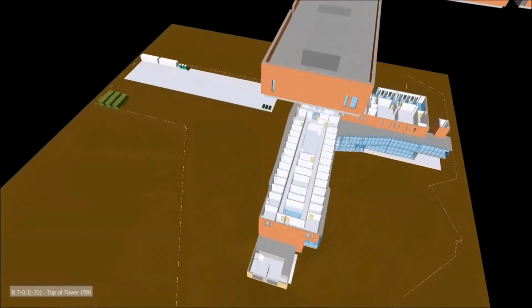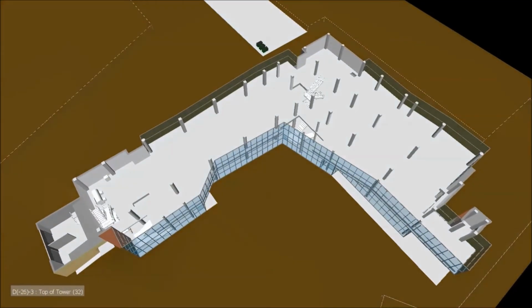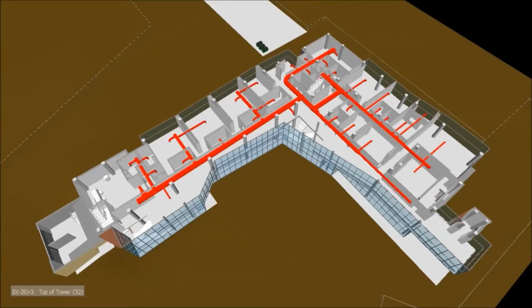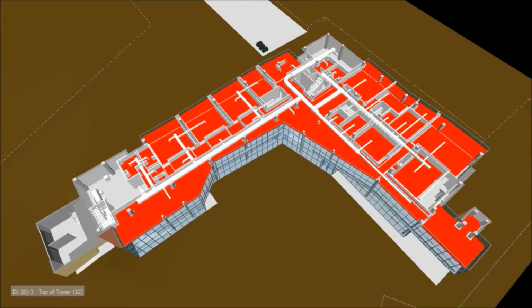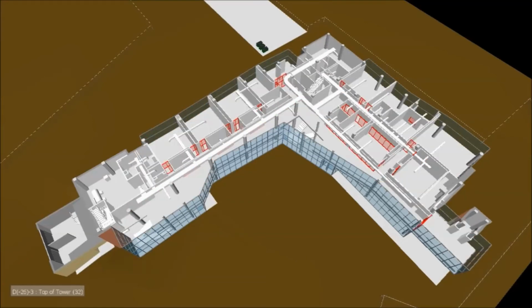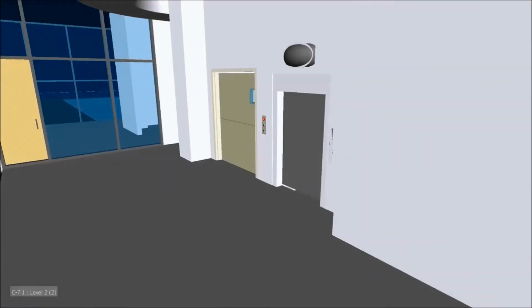Interior construction will start with the fourth floor to avoid work that is in place from being disturbed. The interior construction process on each floor will begin with the walls being framed. Next, MEP rough-in will take place, followed by the ceilings. Afterwards, interior glazing will be installed, followed by the MEP vinyl and trim out. To complete each floor, doors will be installed. After MEP rough-in on the first floor, the passenger and freight elevators will be installed.